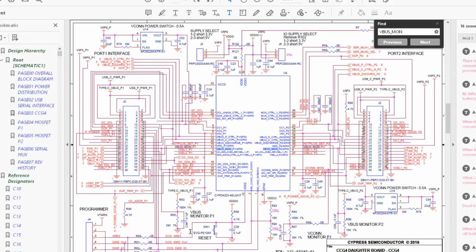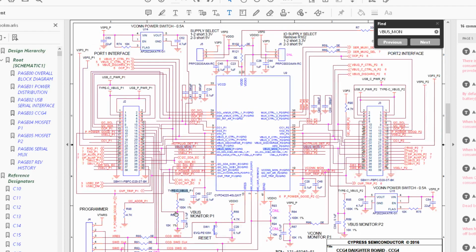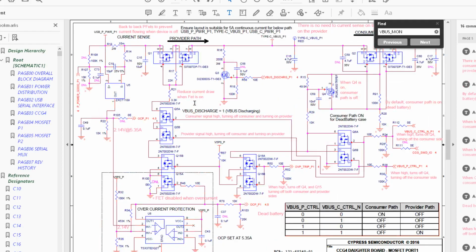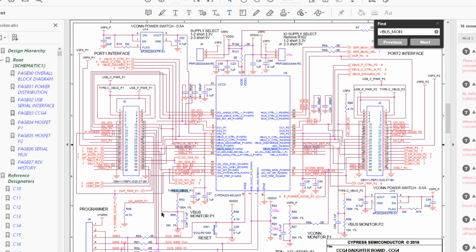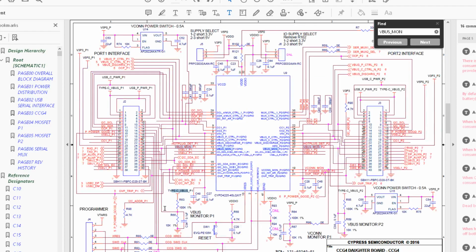There's a V-bus monitoring circuit. So where is that? There. So they've got the voltage divider on the V Type C. This is the output Type C V-bus, which is here. They've got a voltage monitoring circuit here, which makes more sense. So previously they had voltage monitoring only on this bit, but it makes sense to monitor the voltage on this bit and keep this one in regulation, because you've only got fixed voltages. You've got 9, 5, 12, 15, something like that. So yeah, this is Type C, and you do the same thing for both.